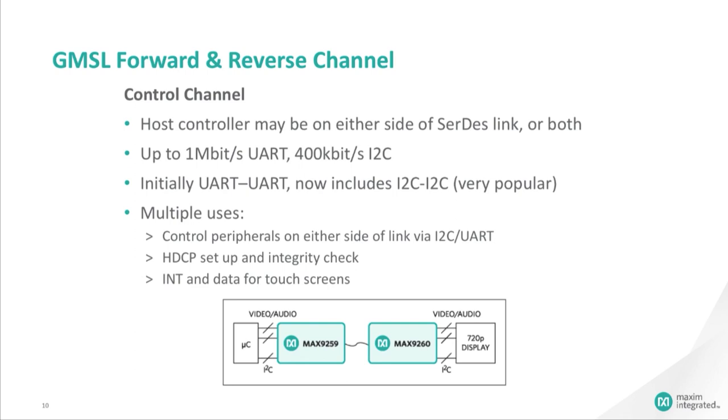The control channel, which is used to configure both the serializer and deserializer, is designed for high flexibility. The system controller can be located either on the serializer side, the deserializer side, or both. Additionally, most SerDes devices support both UART and I2C control interfaces. Allowing different controller locations and interface modes makes SerDes parts suitable for a wide variety of configurations.